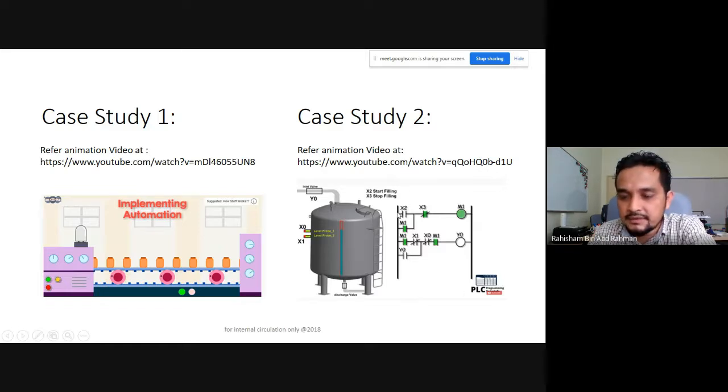Like this one, we have the ladder diagram here. You have a ladder. Okay, rung 1, rung 2, a combination of lots of switches and outputs here, motor, x1, x2, x3, okay, x1, x0, x2, x3. So each of these has a specific function, and they need to know where to be switched on and off in order to operate the system.